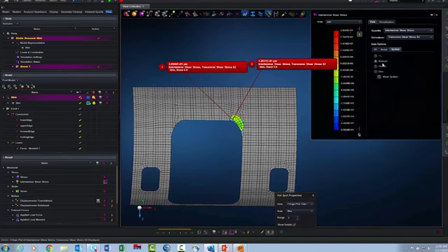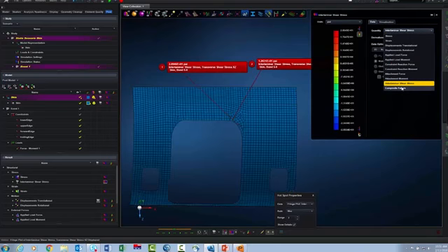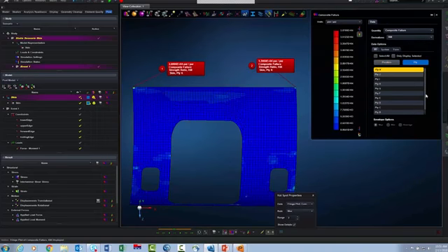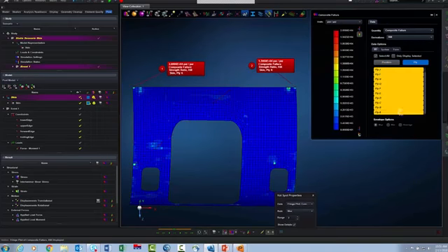Looking at the interlaminar shear stress, this is just going to be in the material system of the panel itself, okay? So I can look at that. I can also look at composite failure. And when I look at composite failure, these are on-the-fly calculations, and let's actually look across all the sheets that